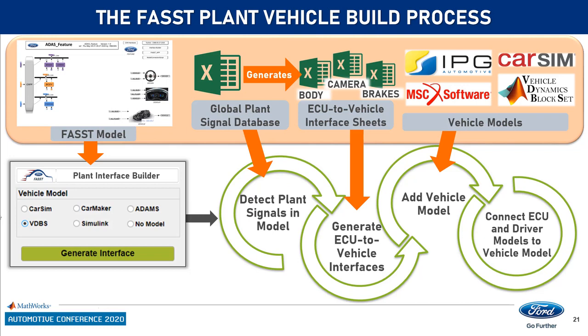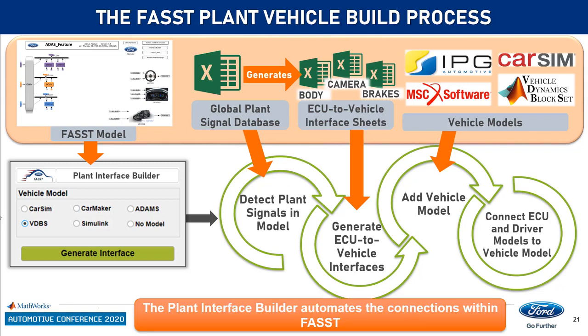The database contains the defined signal names and their appropriate mapping to all the vehicle dynamics packages at Ford. The interface builder then is able to generate the plant interface sheets needed for each ECU component model. The vehicle dynamics model selected in the interface builder GUI is then added to the FAST environment, and the connections between the component ECU model, driver, and vehicle are all done in a matter of seconds. Now the user is on their way to start simulating and exercising their model.